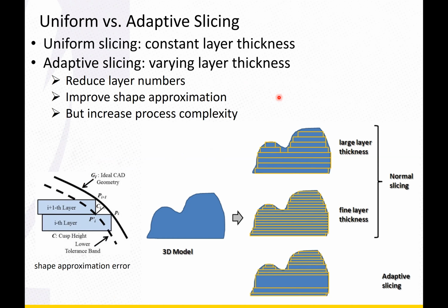So you're going to have to change how long the laser is held in place. And that probably could give you all sorts of trouble with it diffusing out in different areas, as far as your accuracy and how small a feature you could really do. Yeah, so you mean the laser beam size, right? Right. Because even if it's the same size spot and you're holding it longer, it might be diffusing out further. Okay, yeah, that's a point.